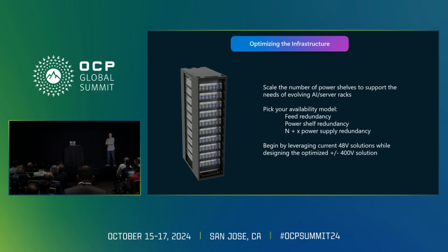Whether that's feed redundancy, what's important to you, power shelf redundancy, do you want to have an extra power shelf or two? Power supply redundancy, do you want an extra power supply in each shelf? Do you want to have some number in the entire rack? It gives you the ability to dial it in just the right way. And what's interesting about this, we can start with today's 48-volt architecture. We can start there while we start building these higher voltage DC, 400-volt systems that I'm going to talk about in just a moment.